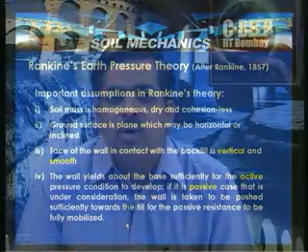We are going to discuss these active and passive states, which are Rankine's states of plastic equilibrium. One is called active, which arises when the wall moves away from the backfill, and the passive state can arise if the wall is pushed towards the backfill.